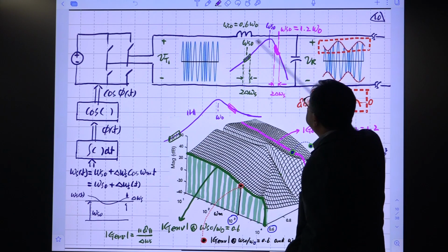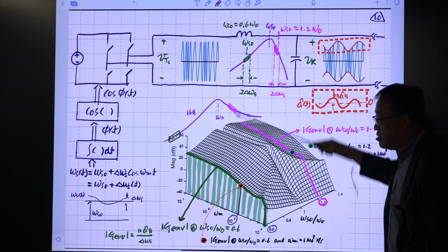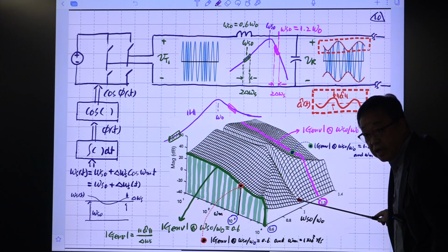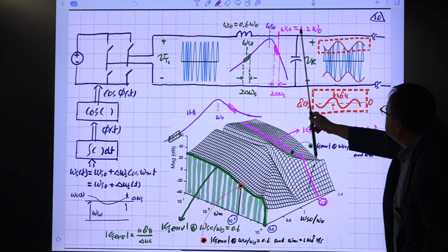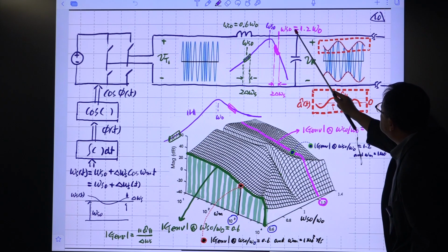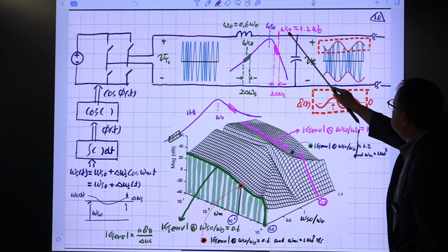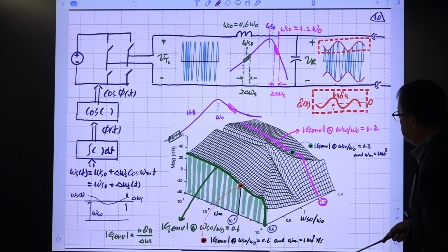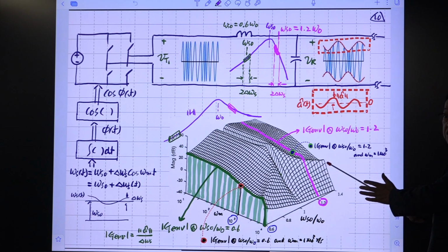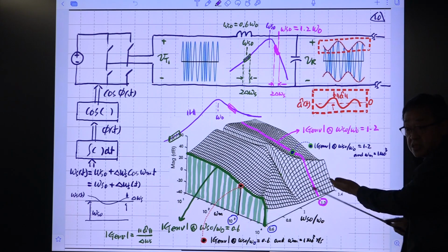Then the slope of this variation is 0, a horizontal part, so this gain is 0. If you increase this, you select this point, and this point is this one. So the ratio between the unmodulated switching frequency and the tank resonant frequency was 1.2. So you are looking at this picture from here. All right, so you are looking at this slope, this curve, in distance.